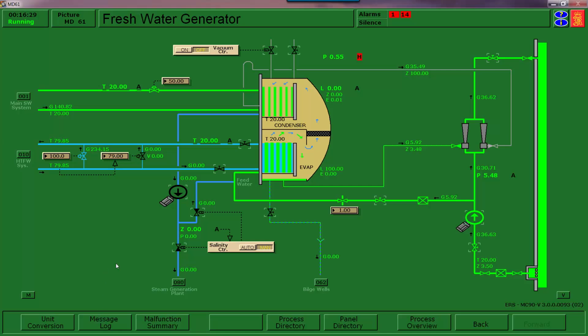So we'll wait for that. Now, the other thing is once I put heat on, then I have to wait for there to be water in the distillate condenser to start the distillate pump. What tends to happen if you start this up with this dry and under a vacuum, you'll tend to airbind that pump and it will not pump the water afterwards. You normally do want to wait for water to build up.